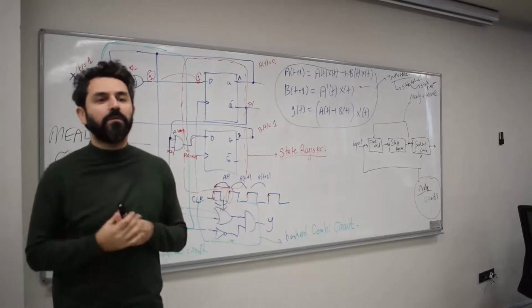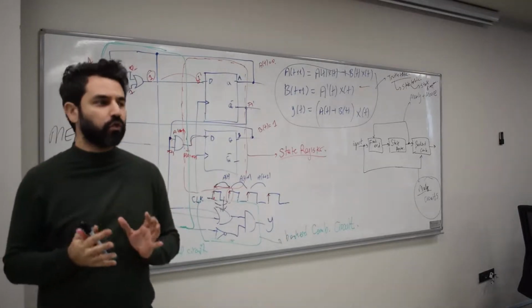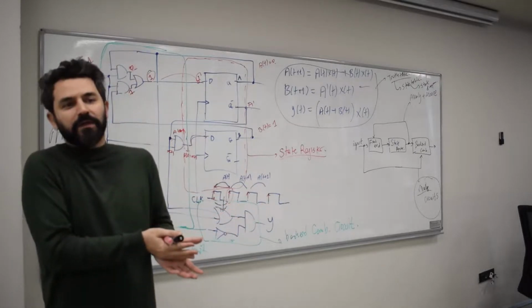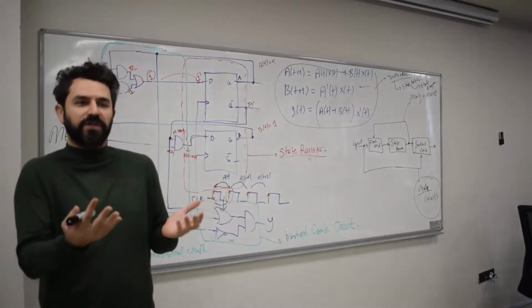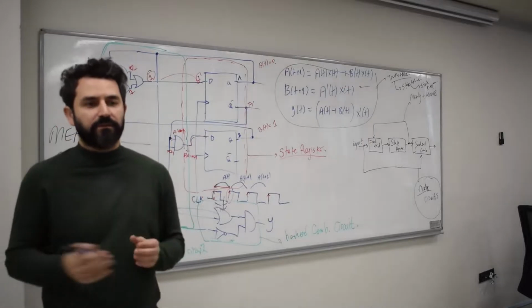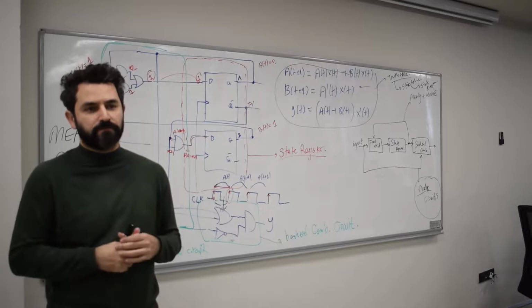Okay? That's the problem. So if you, for example, in the transmitter, limit the number of runs to some number, for example 1,000, then that problem would not happen. Because 1,000 is something that is tolerable from a receiver point of view. So we limit the runs of ones, yes, we limit the runs of ones, for instance.